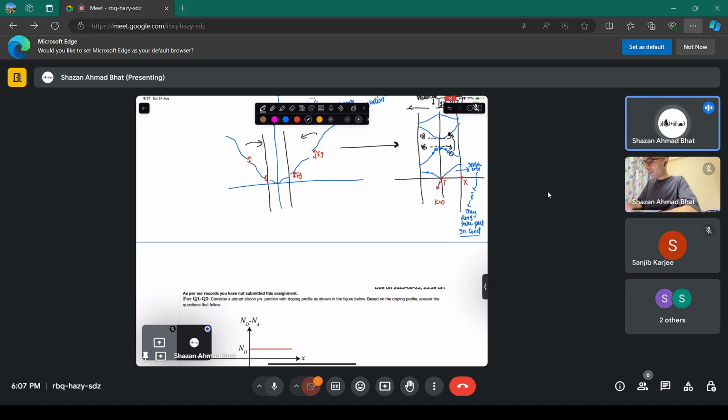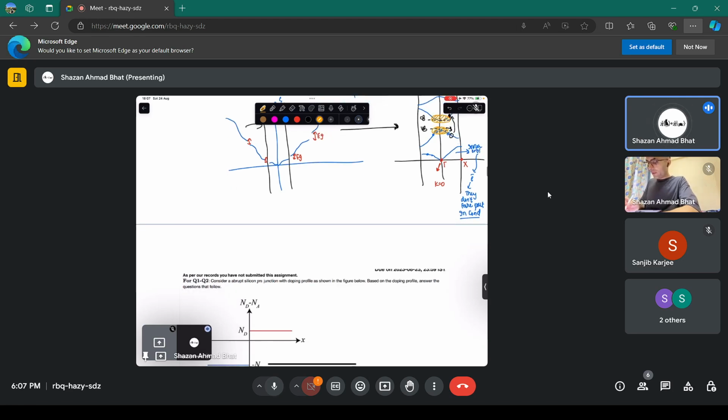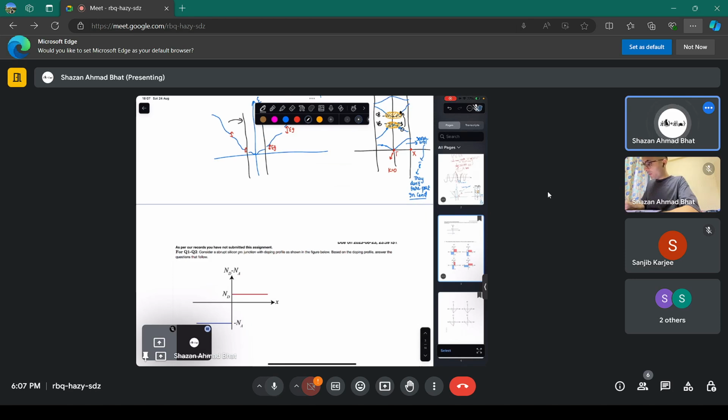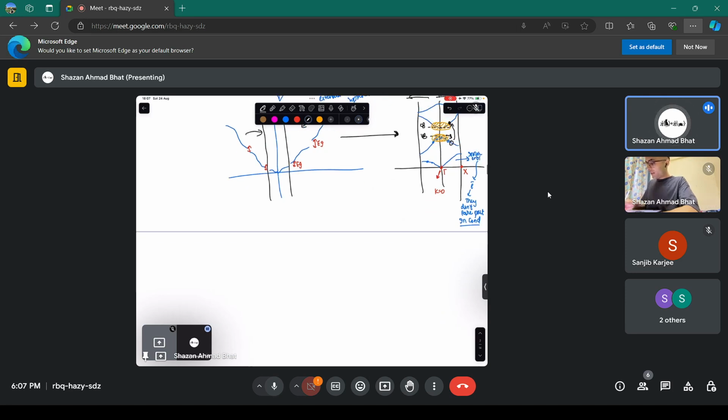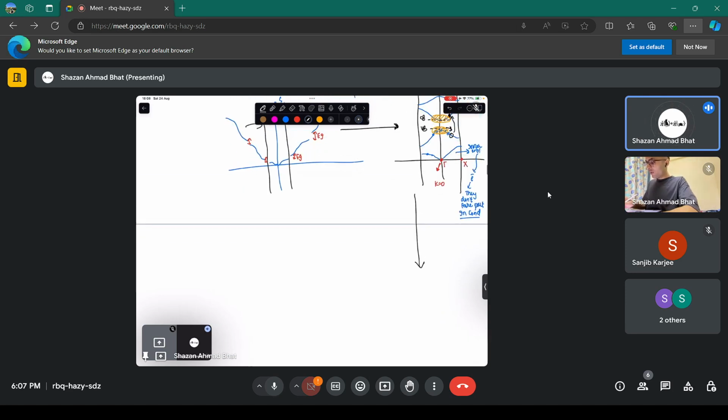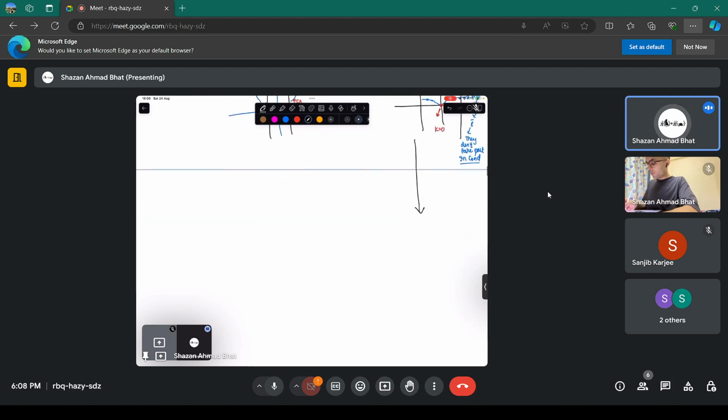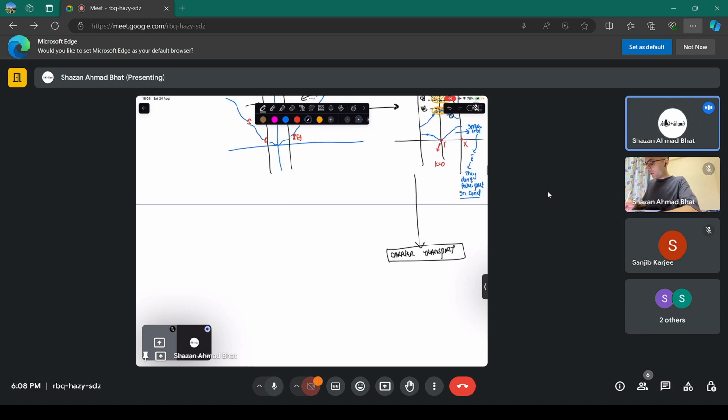Now all of the conductivity happening here is happening in this particular band, and mostly we are concerned about the things happening at these points near k equals 0 of the Brillouin zone. And when you go further into it, just to revise what we studied, we used this concept to understand the carrier transport, which was in the previous week. Now you have understood the energy versus the k space.